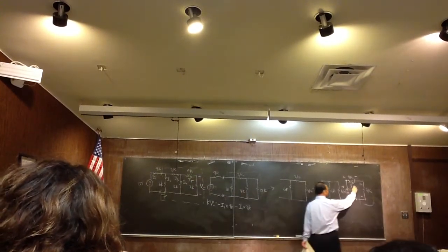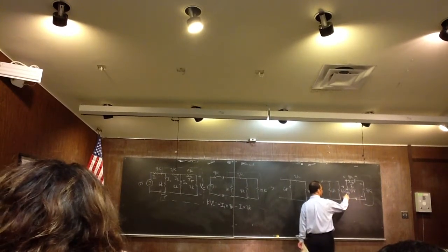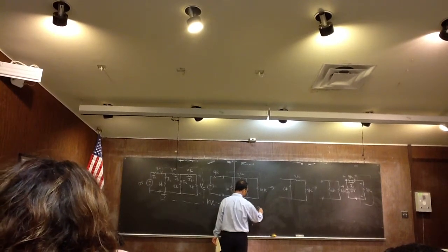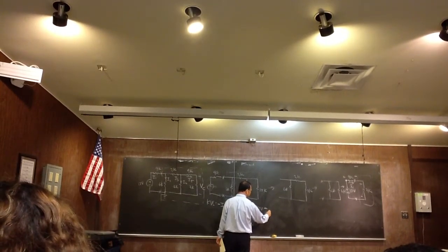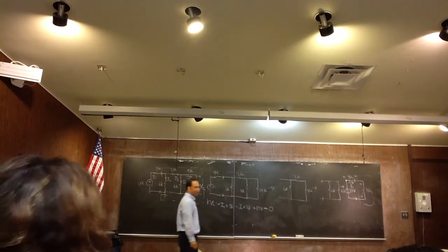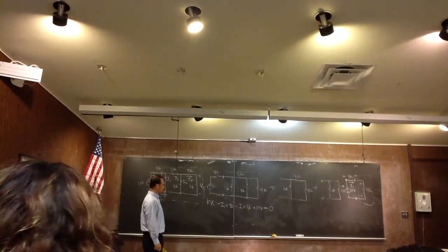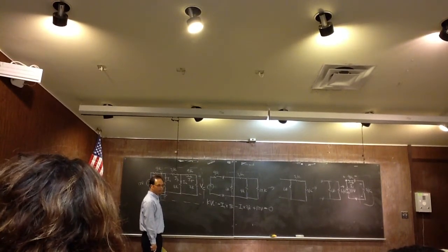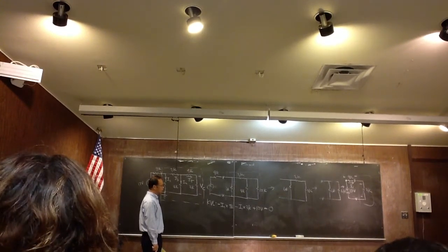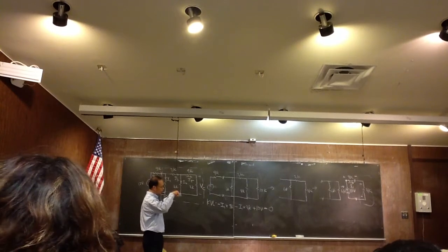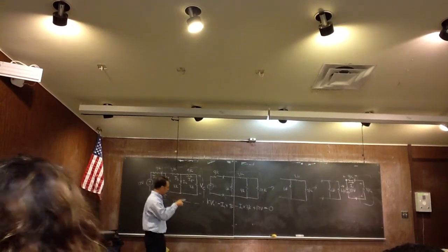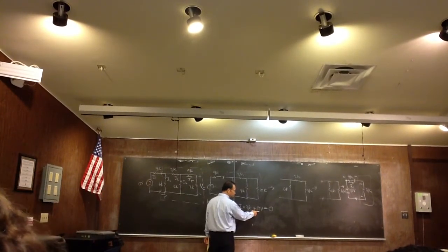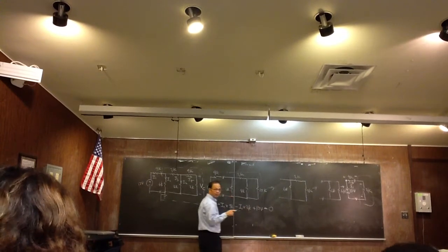And then you go in this direction, right? Now you see a voltage rise. It's a voltage of what? 12 volts. And that has to be equal to 0, yes? That is the Kirchhoff voltage law. So I go around a closed loop, right? And I add up the voltage drops and the voltage rise. And the sum of that must be equal to 0.